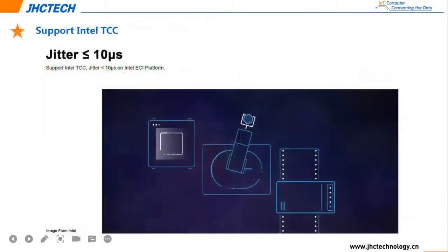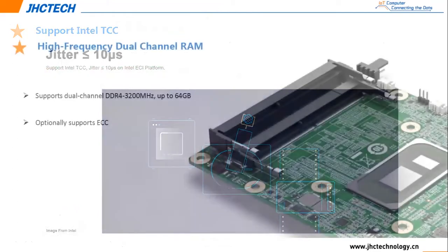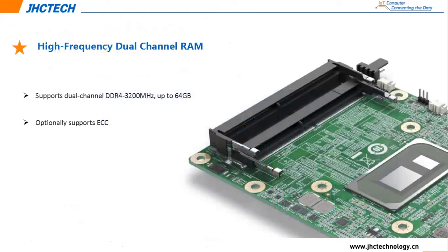It also can support Intel TCC technology, so the real-time performance will be improved compared to before. The timing jitter is within 10 microseconds. It can support dual-channel DDR4 memory up to 64 GB. Optionally, you can choose ECC memory.